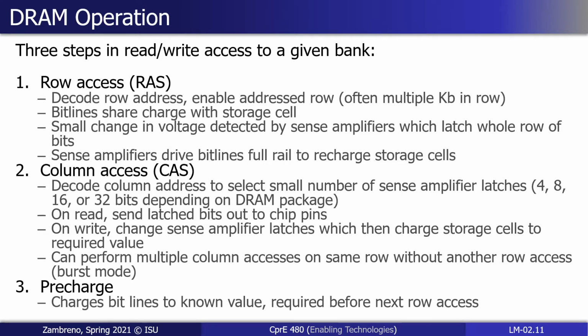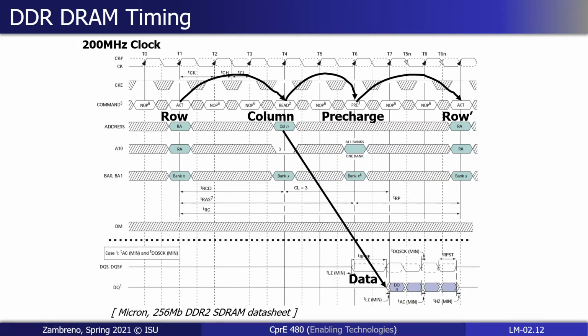Then there'd be a column access side where, depending on what the rest of the bits of the address are, decode that into the actual column or columns that we want. All while periodically, because of the fundamental nature of DRAM, charging those lines so that we don't lose information stored in that memory. Those DRAM controllers become pretty awful quickly. Here's just a semblance of a DDR1 initial generation DRAM timing sheet, and a very small part of that.